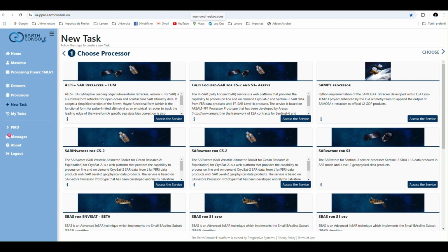As its name suggests, the SBAS approach relies on an appropriate combination of differential interferograms produced by data pairs characterized by small temporal and orbital separation baseline in order to limit the noise affecting the interferometric phase signals.